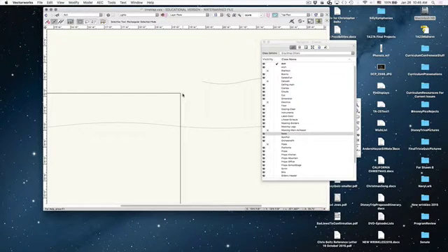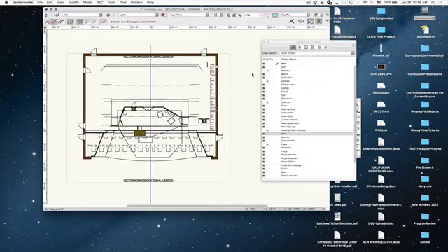And so when a snap says, when my mouse gets close to an obvious thing that I want to connect to, go ahead and snap my mouse, my pointer there. Okay? So when I've got snap others on, it means that I can snap to objects that are not on my active layer. Okay? Show others means that I now can see things. I'm looking at my visibility here. So whatever visibility it is, okay? Show snap others, I'm going to see it and I can snap to other things.